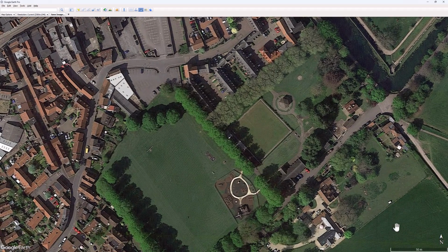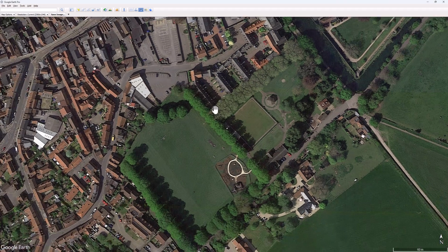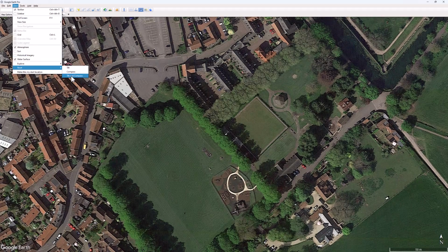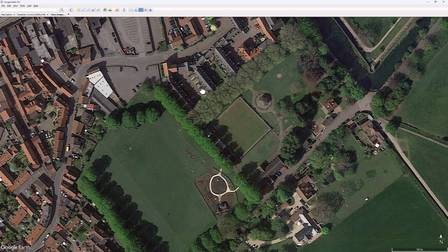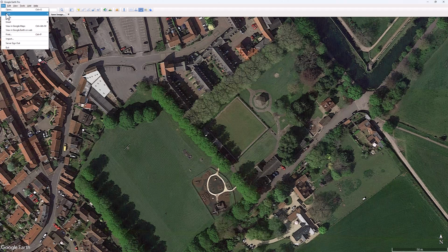if you would like. Now, the thing that's missing from this are trees. And so to get that, what we're going to do is go into Google Earth. I'm using Google Earth Pro, but you can take a screenshot from Google Earth if you want. Just make sure that you have reset the tilt and compass so that it's actually oriented north and that it's not rotated in an incorrect way.